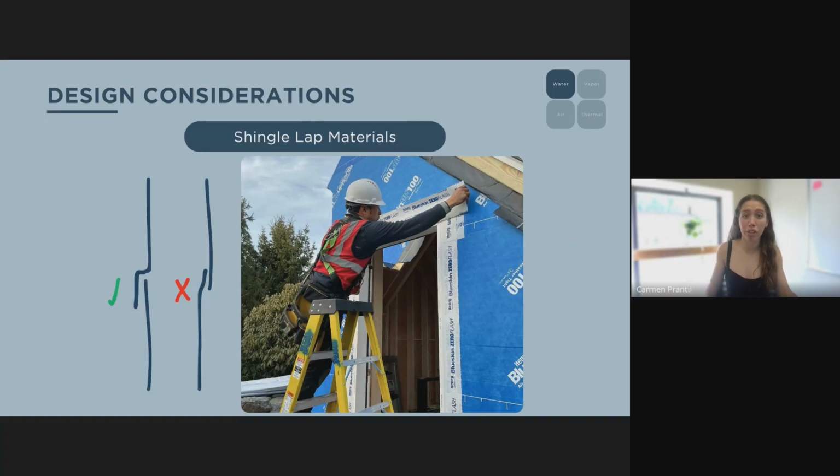And then any water that's running down, again, that drainage plane with gravity could get into, in between those materials, getting to the sheathing or getting into the wall assembly instead of guiding it out and away. So when you have reverse laps, you have to continuously seal or terminate that lap with sealant or with mastic.